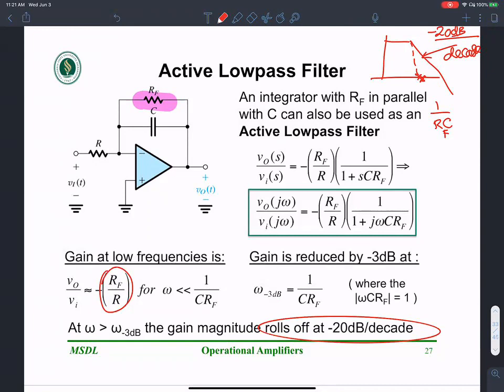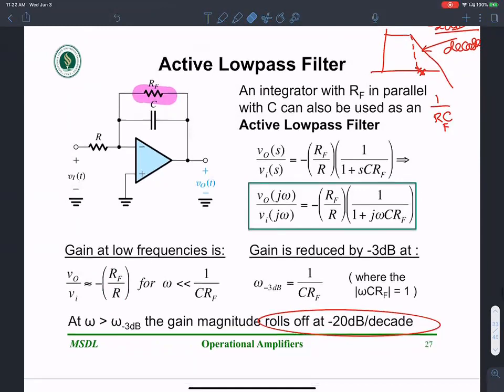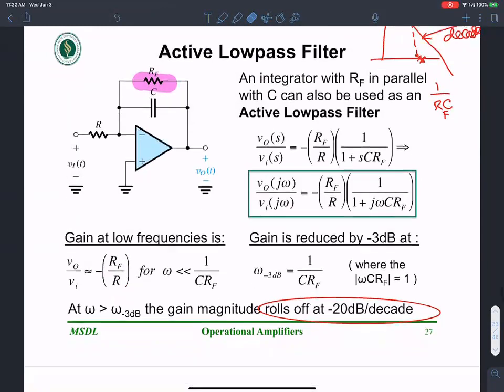Okay, the voltage across this guy is going to be L di by dt, and that is what sets the behavior of this circuit over here. When I have an inductor in place of a resistance, the governing equation becomes V is L di by dt. And based on that equation, I have a different behavior. So, can we call it now a differentiator? I'll have to look into that and see if it behaves like L di by dt. I'll have to take a closer look.